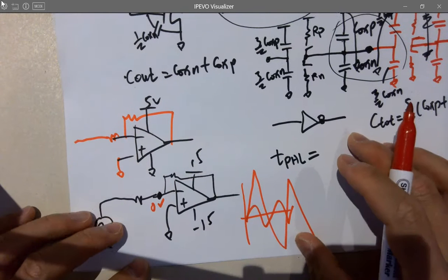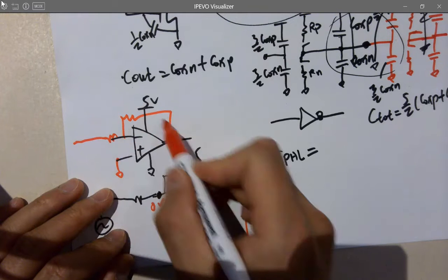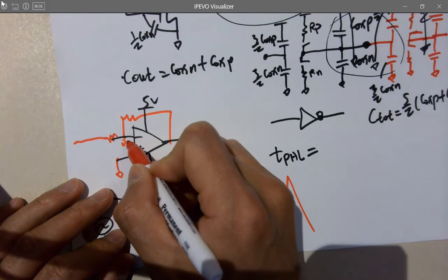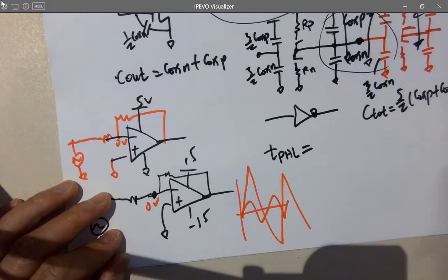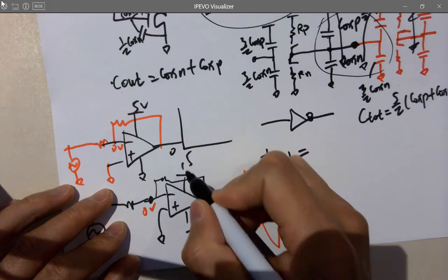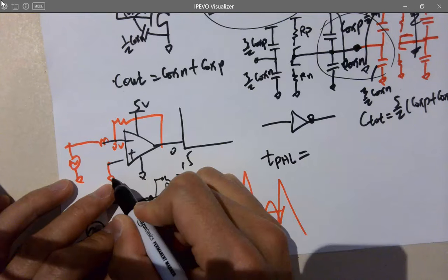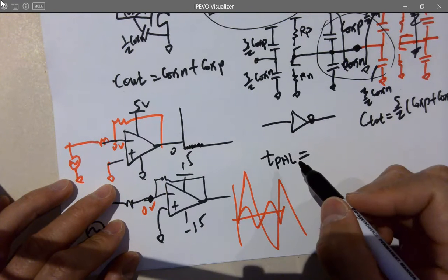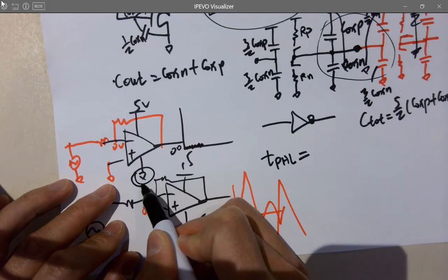No. If you ground it, it's a negative feedback, so it's going to drag this voltage to a voltage very close to 0 volts. And you get a voltage input, then what's going to happen? Your signal, so here's 0 volts, for example. You want to swing your signal, forget about it. It got 0 as a DC offset, as a baseline. The signal will never swing to anywhere. 0 volts is the lowest potential in the circuit.